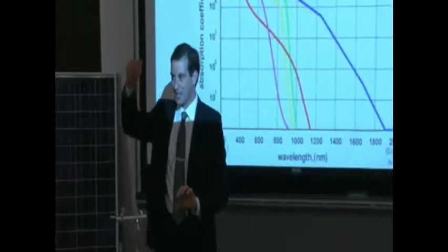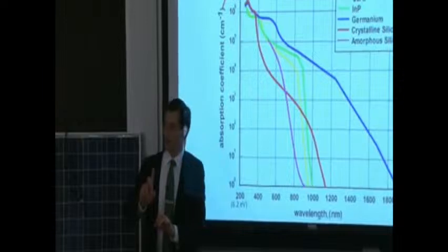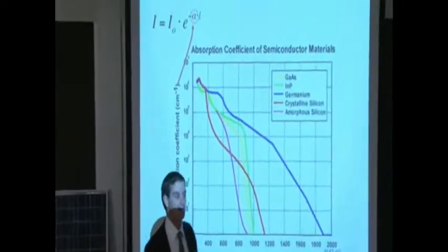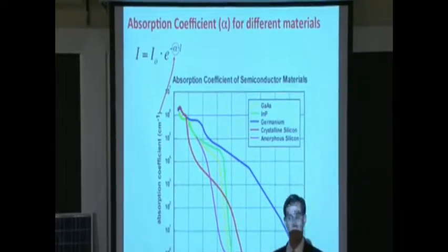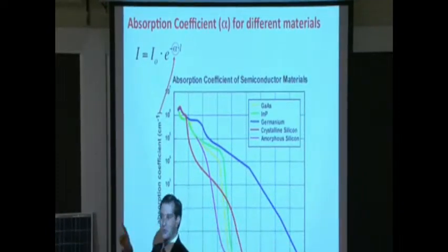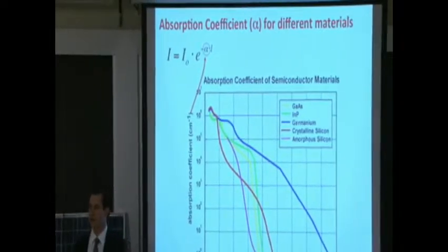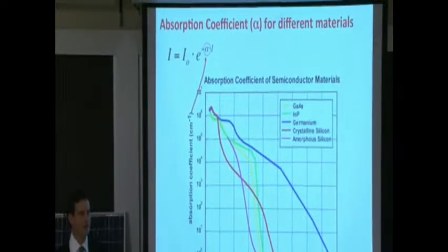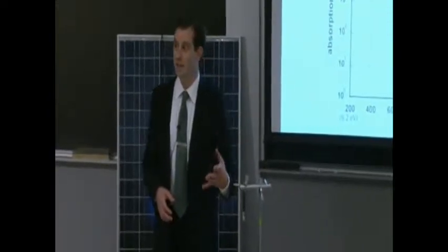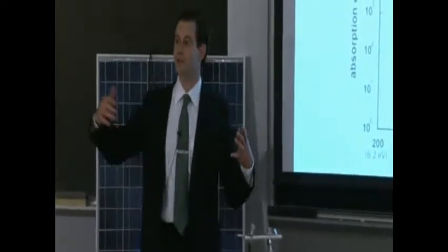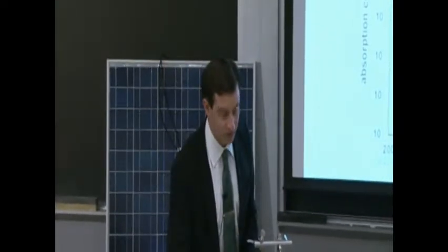Yeah, so if the light goes through the solar cell and doesn't get absorbed, that 10% of light that didn't make it, that's going to get reflected back. It's going to get another chance to go through. So if you absorb 90% of the light on the first pass, you'll absorb 99% of the light on two trips, two optical path lengths through the material. And so the term optical path length is a very important term here, because the optical path length does not have to be the thickness of the material. Ideally, the optical path length through the material is much, much thicker than the actual material itself. And over the next few slides, we're going to learn how we engineer that.